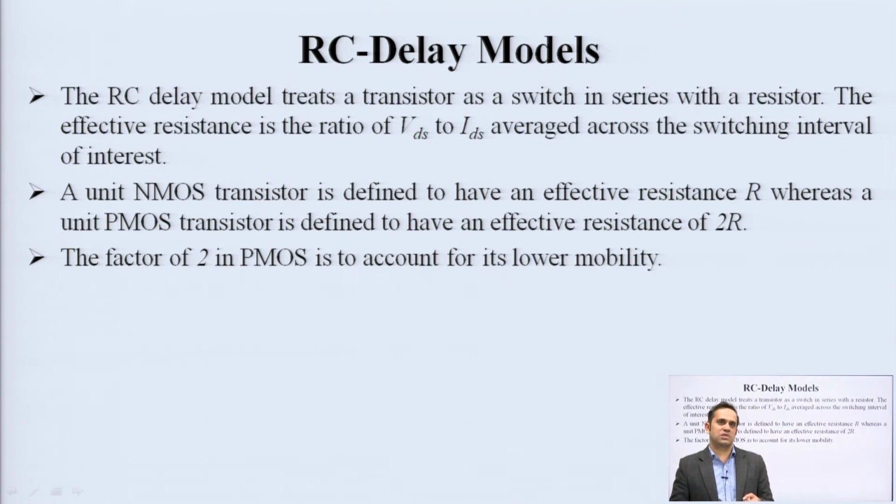Conduction in an NMOS transistor is because of electrons, and because of the energy band models, holes tend to have a higher effective mass and hence lower mobility. So, holes tend to be heavier as compared to electrons. This produces lower hole mobility as compared to electron mobility.